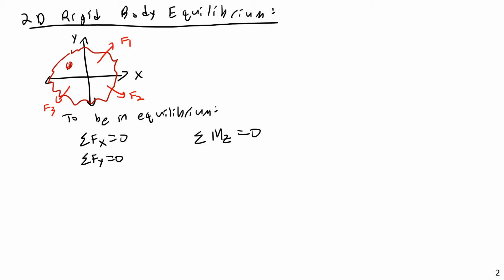So if you place that on the 2D plane, for any given force, no matter what the direction, you can see that the moment vector for any force on the 2D plane is going to be directed either into or out of the page, depending on what direction it is going about whatever point you're taking moments about. So the moments generated by any force in a 2D problem are going to be pointing either into the page or out of the page.